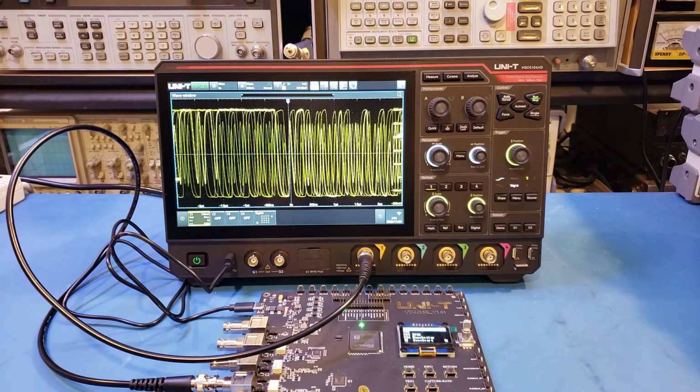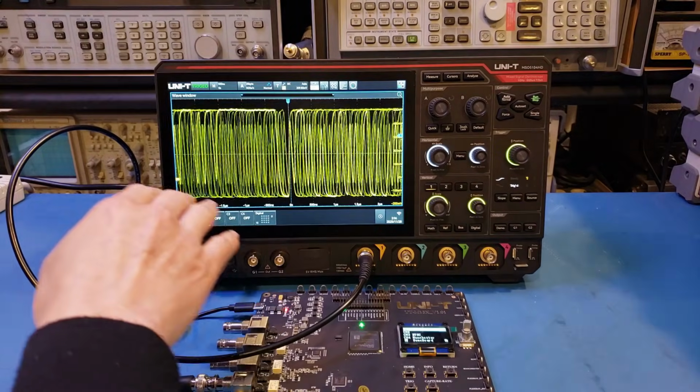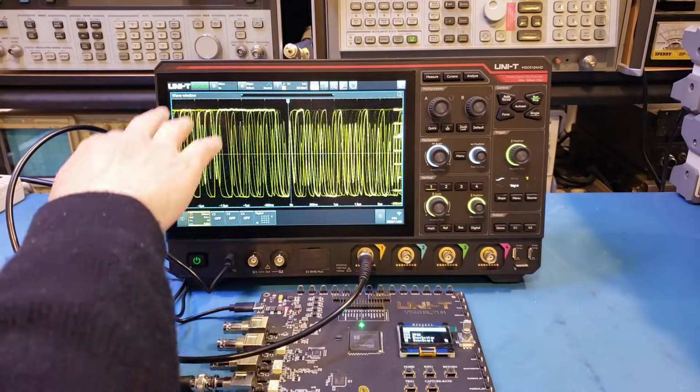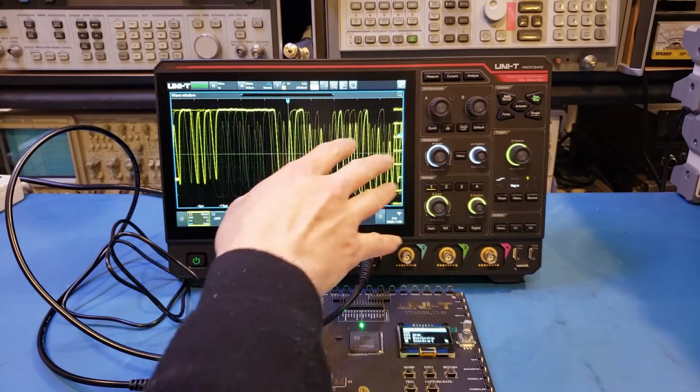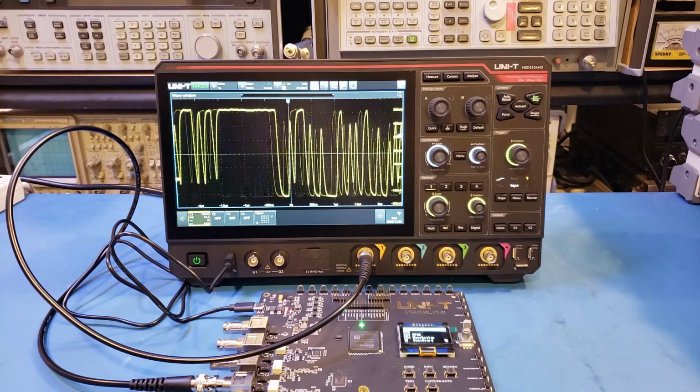The first signal we're looking at here is a runt pulse, and right now we're just triggering by edge. Of course, we are not able to totally stabilize the signal, because even though we have this trace that is somewhat stable, there's some garbage displaying in the background. So the goal is to obtain a stable trigger. Let's take a look at how we do that.